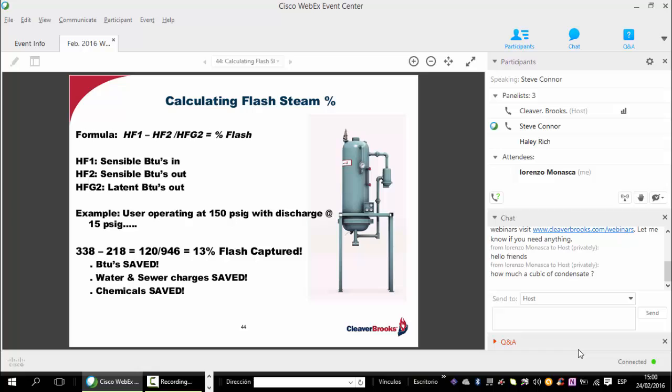So it's very, very possible in condensate lines to incur differential water hammer, which can be extremely dangerous. And it's something that we definitely want to be very careful about. And that's why it's so important that we maintain proper velocity and proper line size, condensate line size, to reduce that velocity. That's why I said, boy, the larger the better.